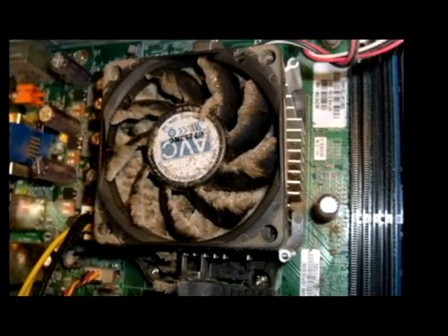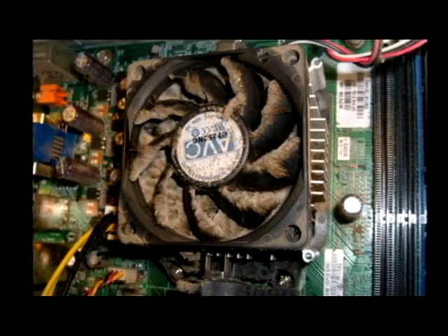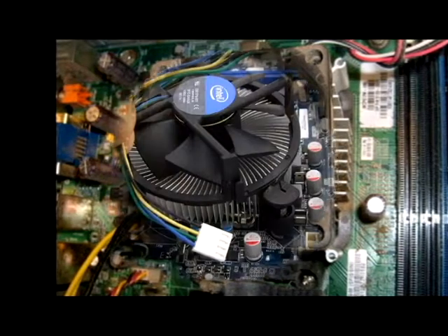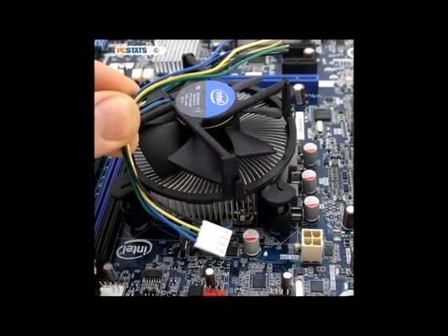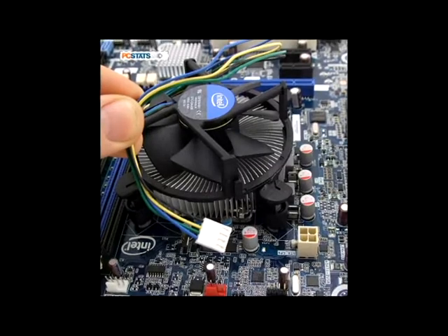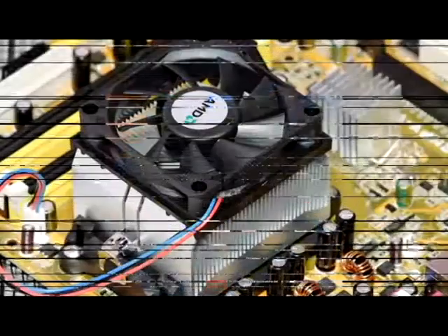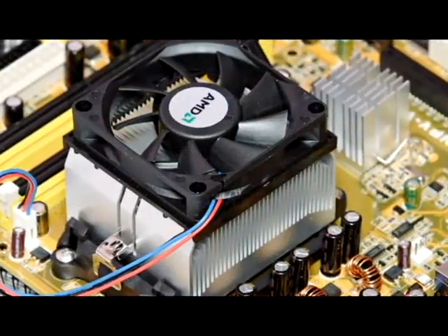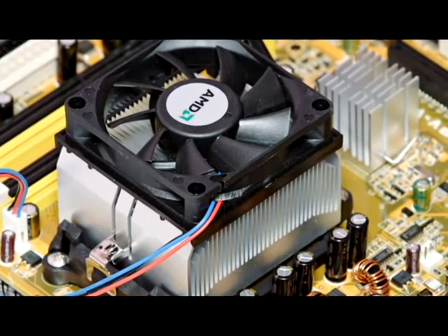If not, remove the processor and see if there's any physical damage to it. Keep in mind that you will not always see physical damage on a bad CPU. If you don't hear a beep at all, more than likely it's a failing power supply or motherboard.